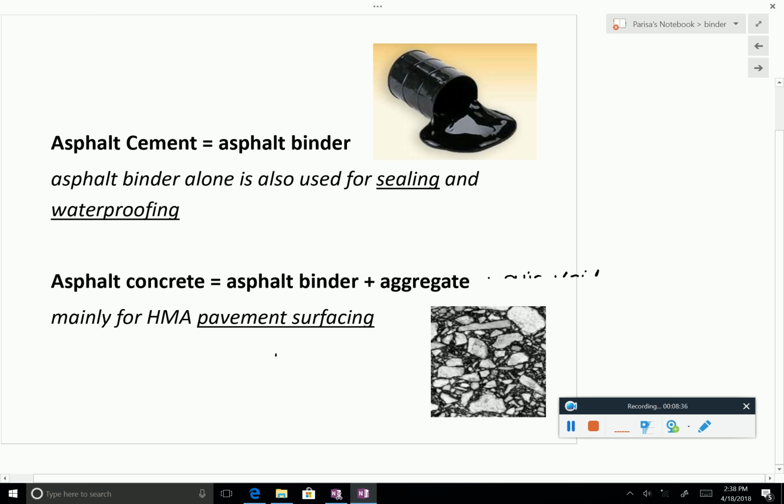Okay, now that I hope you are convinced that asphalt concrete is a good material, used for many miles of roads, let's find out what it is. Typically, people just say asphalt, but asphalt is not asphalt pavement. They miss the ingredient, which is very important, and that's the aggregate. If you just say asphalt, then you are just talking about the sticky black flowy material. So it's not what you see on the road. If you just use that, everyone would sink in, and there would be no pavement. So we want to learn to use the technical terms as engineers.